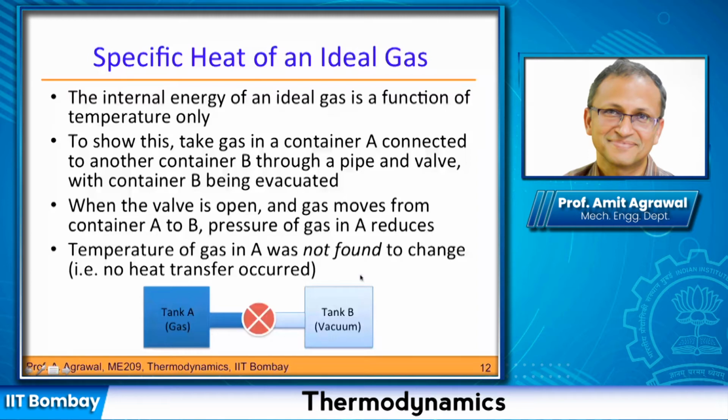Now, what was found is that the temperature of the gas in A does not change. That means that there is no heat transfer that has happened in this case. And of course, this is a gas which is expanding in vacuum, so there is no force which it works against. It's just a free expansion.